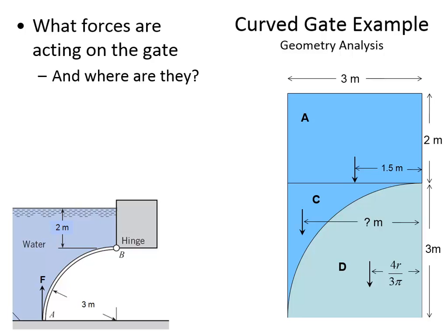All right, so what we can now do is find the area moment of inertia. Remember, that's A B cubed divided by 12. A is the horizontal measurement of 4 meters. B is the vertical measurement of 3 meters cubed divided by 12. The area moment of inertia for this gate is 9 meters to the 4th.